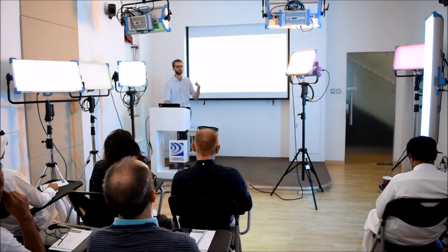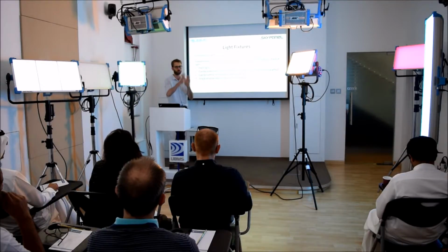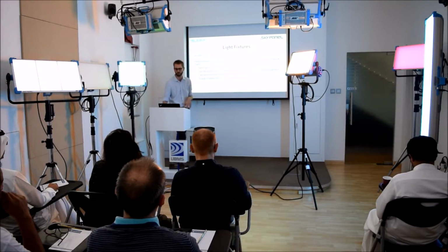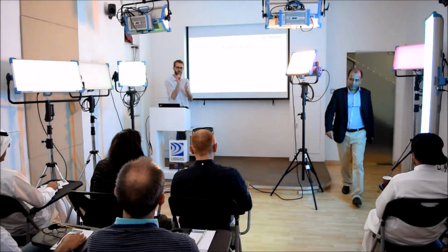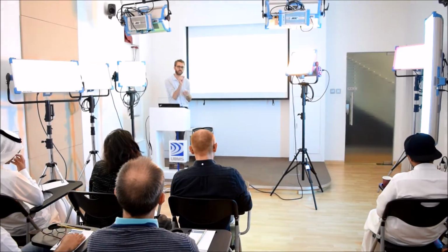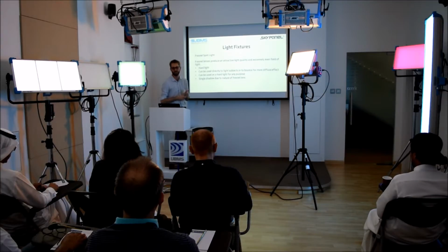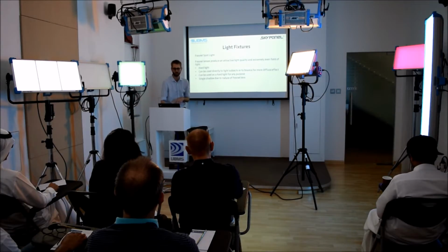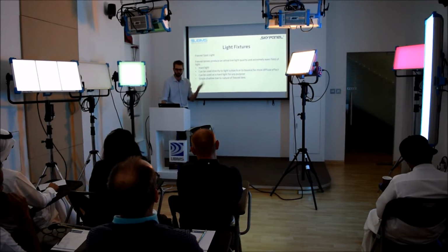That's actually a downside to some of the earlier LEDs as well. Some of the earlier LED panels, not from ARRI but from others, would give you multiple shadows depending on how the LEDs were used. Because if you think about the older panels, the ones with those little LED lights in an array, every single little LED is a little light source. So every one is going to produce its own shadow. And that's something that the SkyPanels from ARRI totally get around. But some of the earlier ones did that. So a Fresnel spot gives you a single shadow. Beam can be focused, obviously, spot to flood.